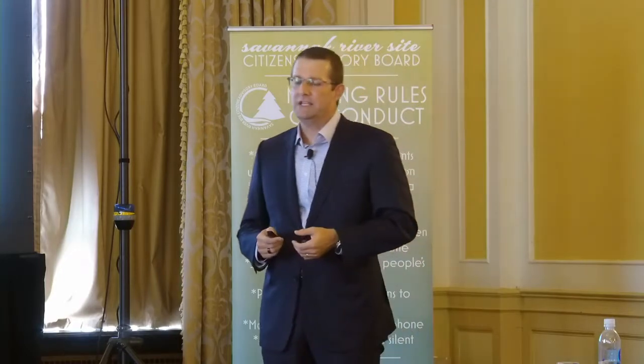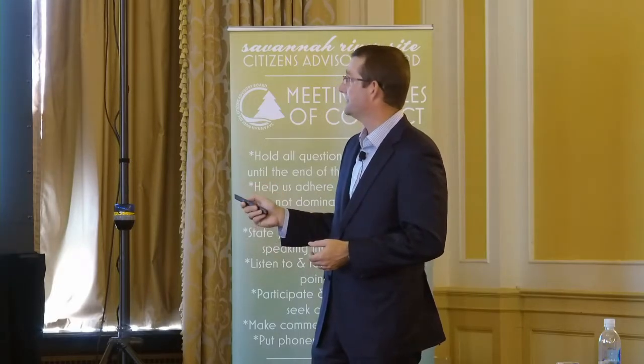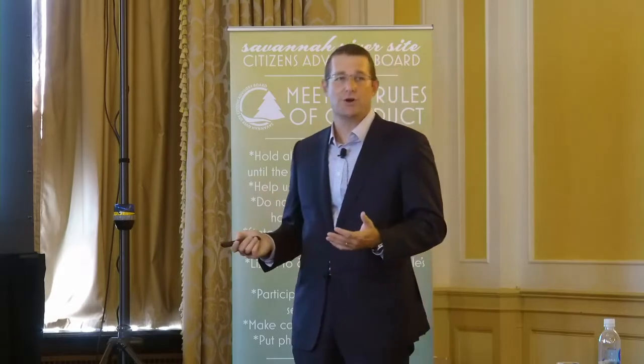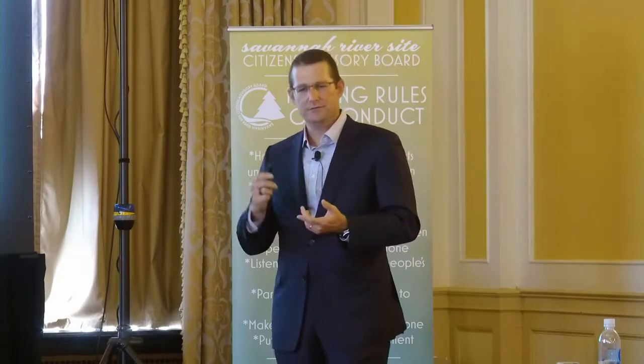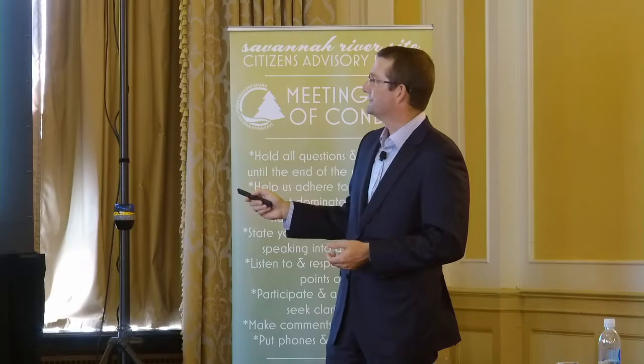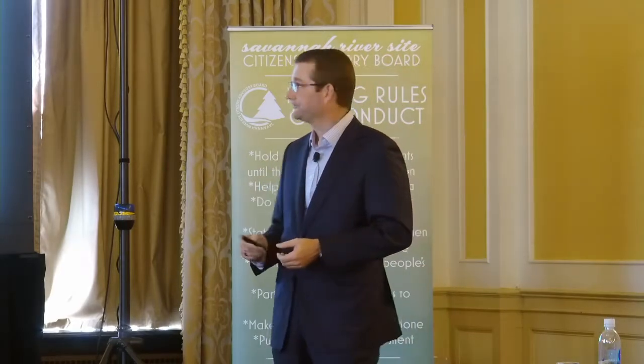So if you have the potential for a hose rupture, what does that mean? Well, when you have a loss of hose integrity, the first thing we're going to do is shut the process down and flush all of our critical equipment. The mixer is an expensive piece of equipment. We want to flush that. The hopper is a custom-built tank. We want to save that. And ultimately, to do all that, we would desire to flush about 1,800 gallons of material through the process.